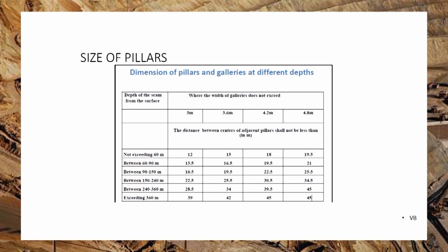Same for the depth 90 to 150 meter and gallery widths of 3 meter, 3.6 meter and 4.2 meter, the pillar sizes are 16.5, 19.5 and 22.5.